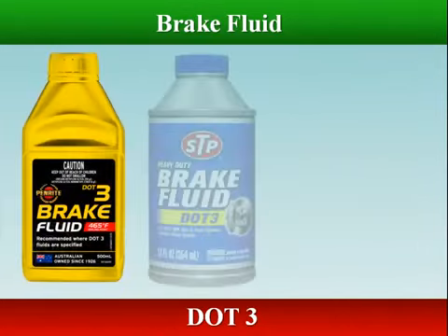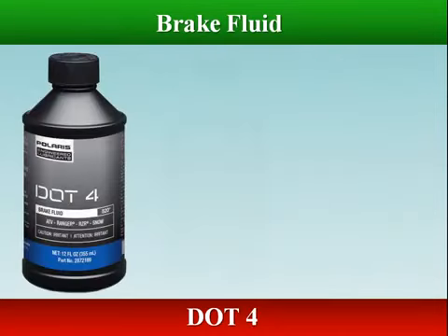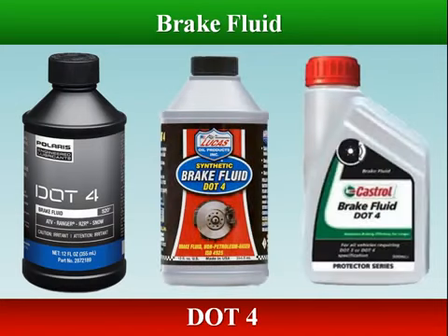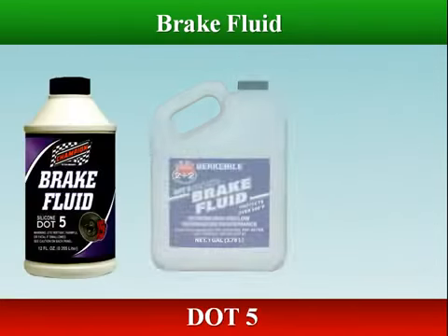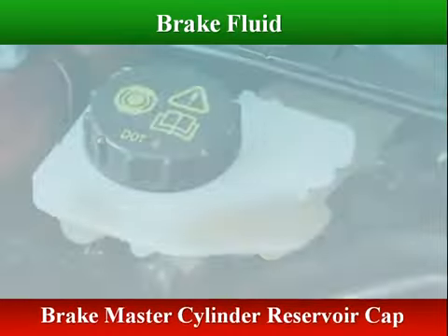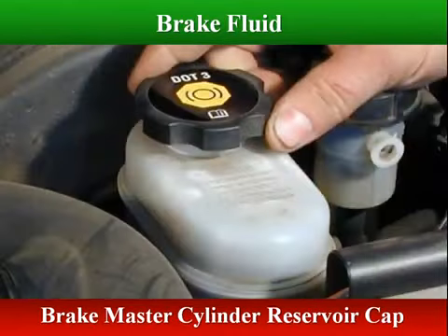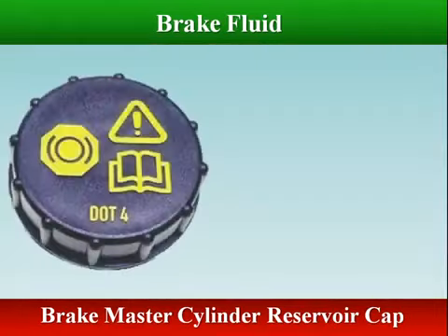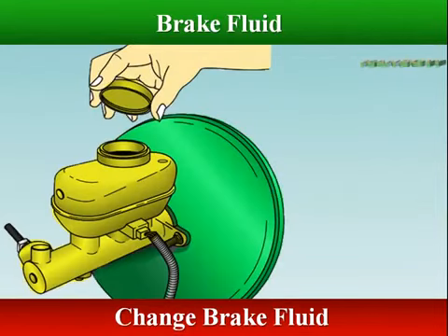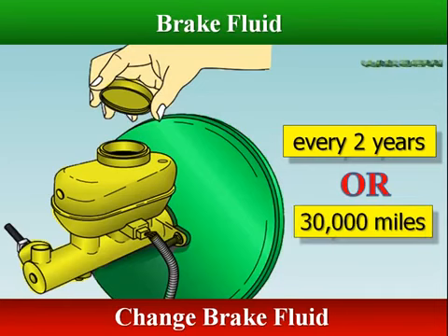DOT 3 and DOT 4 are glycol-based, most common in use, blend with each other, and are hygroscopic, absorb water. DOT 5 is silicone-based, not compatible with glycol-based fluid, and is not hygroscopic. Most modern cars have the fluid type printed on the master cylinder filler cap. Most car manufacturers recommend changing the hydraulic brake fluid every 2 years, or 30,000 miles.